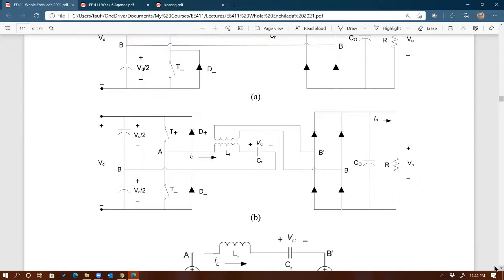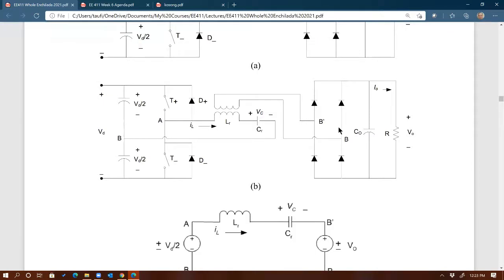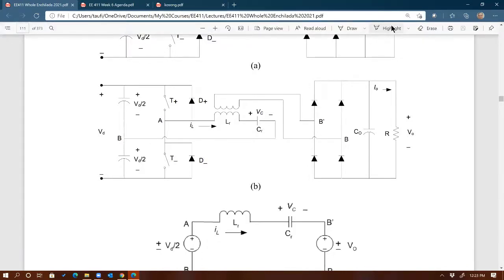It was a pretty interesting design, high power, high voltage. And especially for high voltage, high power, this is the type of topology you want to use for that kind of operating parameters. Input is 3-phase AC, and output is high voltage DC, 40 kilowatts. This would be an ideal candidate to do the job. Especially for the high voltage, remember this is plus minus 120 kV.